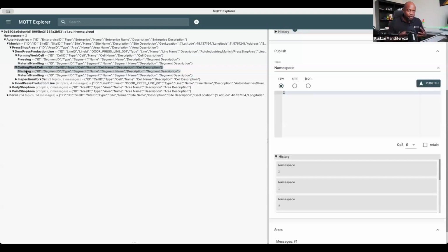Another real benefit of creating these process segments is that you want to be able to group those pieces of equipment. So again, to that example, in the material handling process segment, you've got a robotic arm and a conveyor, and you want to group those related resources under that specific segment. That's also an ISA 95 specification that allows you to view all of that information, to exchange information effectively between your shop floor and your top floor.